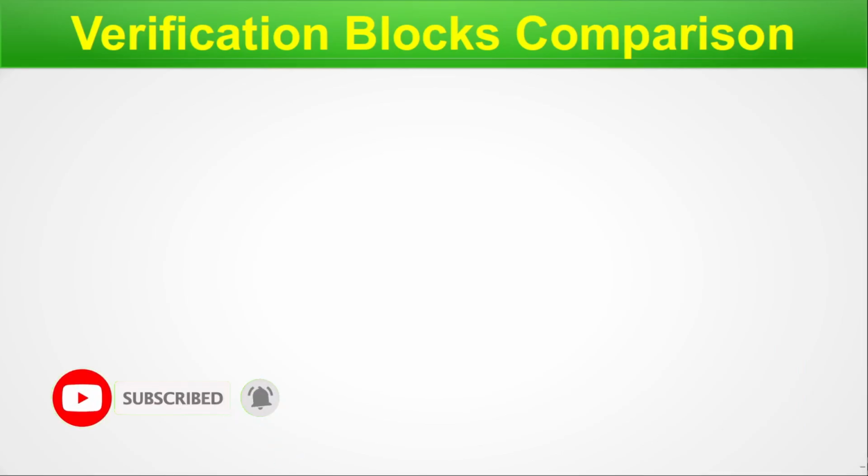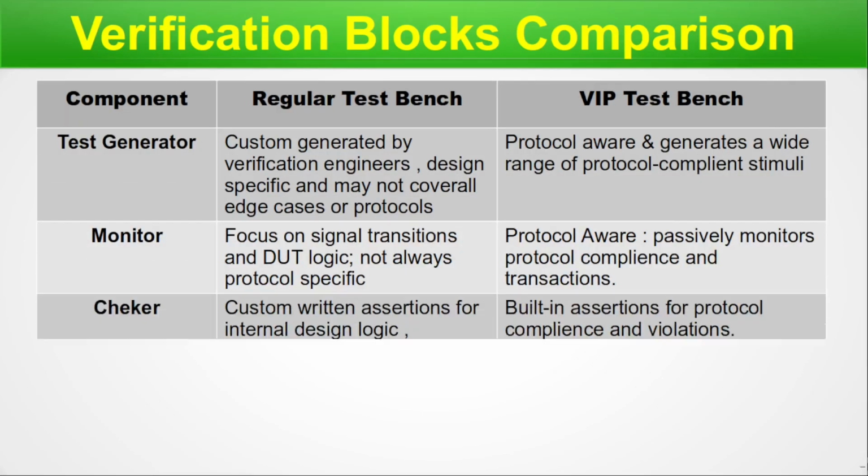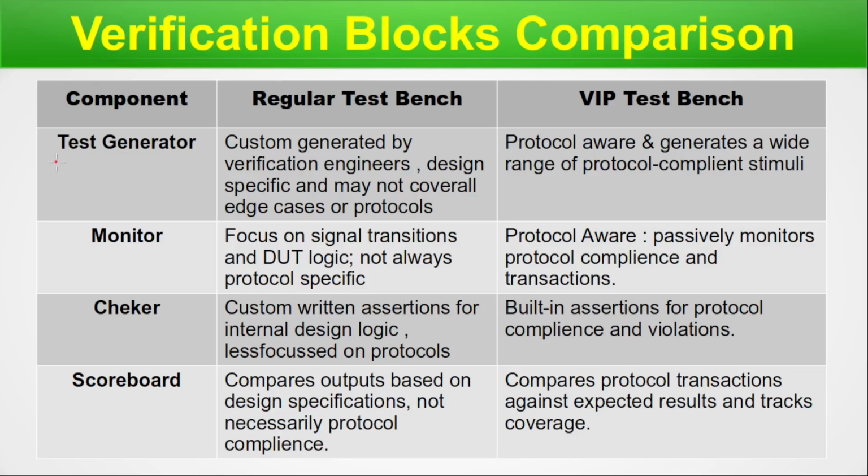Verification blocks comparison. Now here in this slide, we will do a comparison between a regular test bench designed by a verification engineer versus a VIP that is very much specific. So here is the table. First, we compare the test generator. For a regular test bench, it is custom generated by the verification engineer, design specific and may not cover all the edges or cases of protocols.